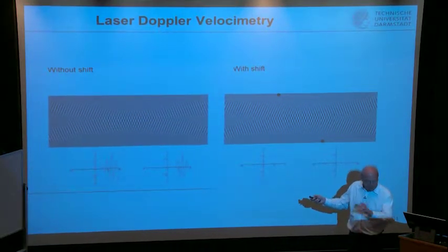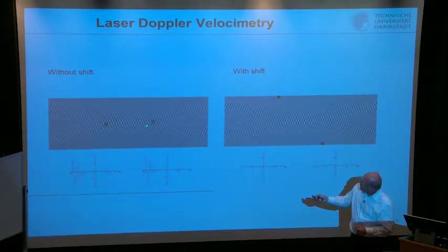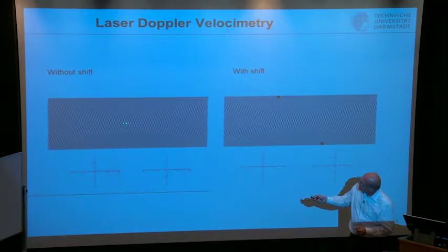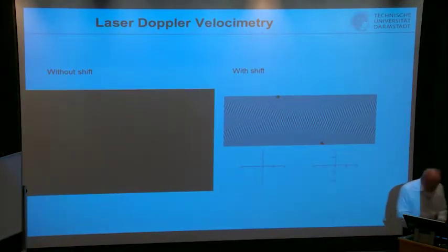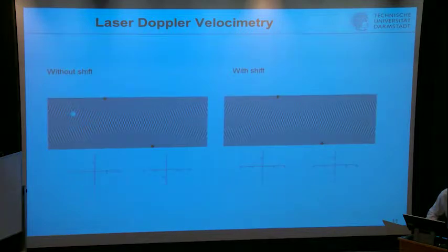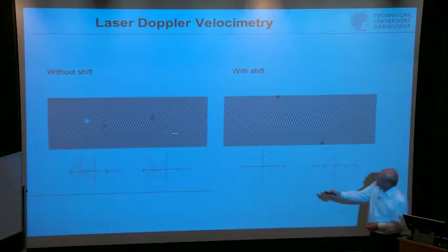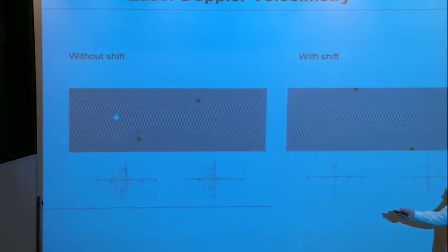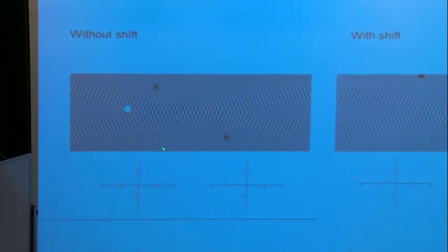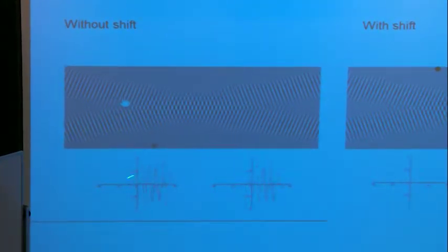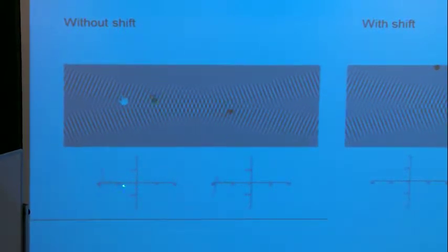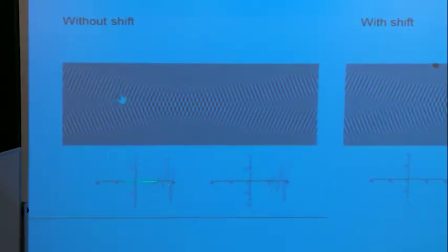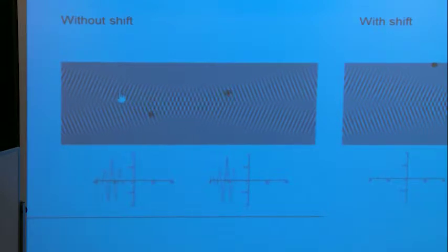Yeah, this is hugely magnified. And then, however, you see as well these stripes. That would be a constructive interference. Yep. But you see as well these gray areas over. This is destructive interference. And then the particle A and B from top and bottom, that would give rise here to Doppler bursts. They are now made symmetric with the same frequency. And this is now different.